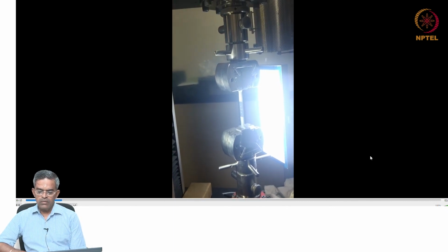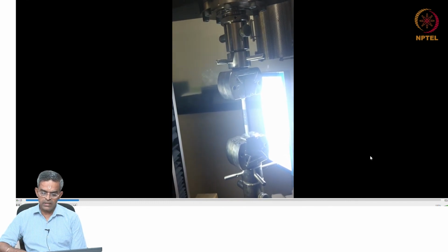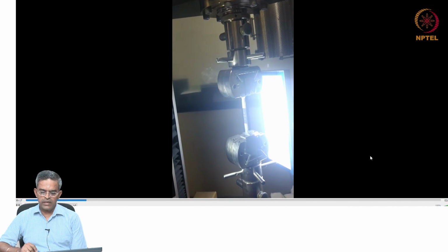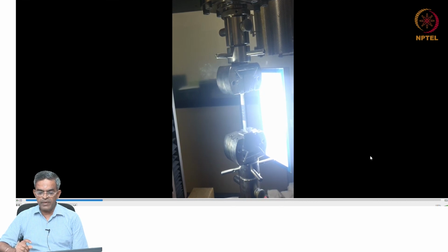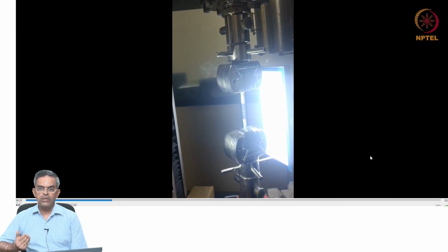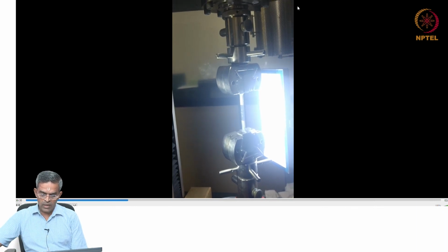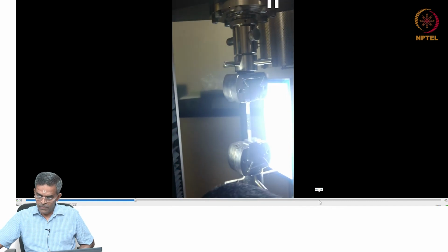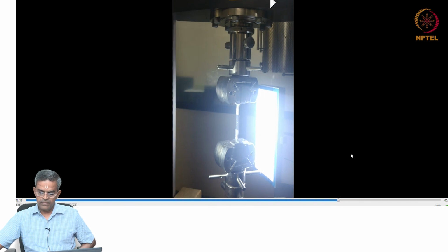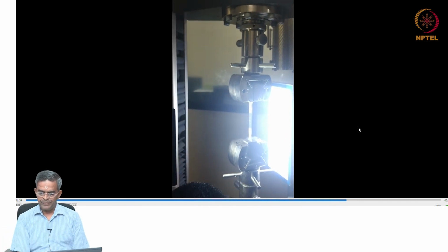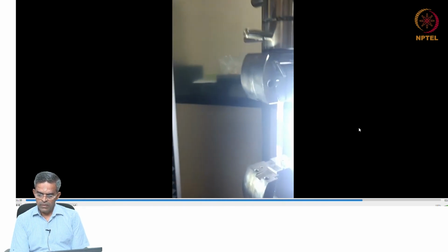There are two pivotal points which are placed along the longitudinal direction and two along the lateral direction. There are 4 points you can see, okay. So, these are the gauge points where we are measuring the elongation and computing the percentage elongation. So, it is a high speed camera which is recording this, the system is being loaded now. You can see the specimen very close at this moment. So, the system is applying an axial pull.